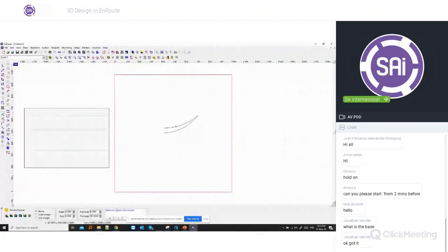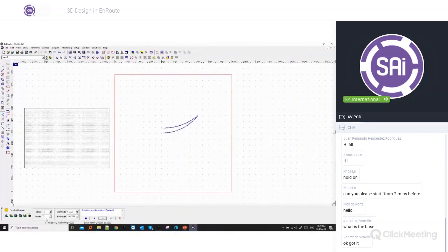Here it will ask us to select our contours that we're going to want to revolve. So we'll do that here. We can select an axis of revolution, but we're not going to do that in this case. We'll have our start and end angle. So I'm going to revolve this 360 degrees. And for this one, I'm going to create a mesh object.